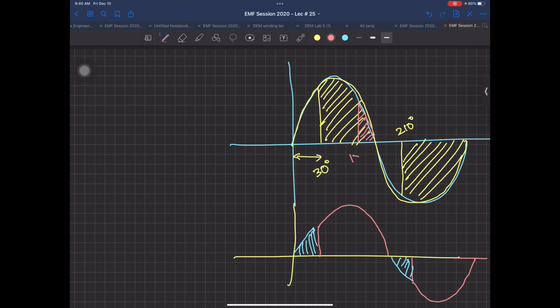So only this portion is going through, and this portion of the voltage is so discontinuous that the current going towards the fan is also discontinuous. So the machine is only rotating, and you can even count the blades of your fan lying underneath it. So the dimmer is actually changing this angle from 0 to 180 degrees.